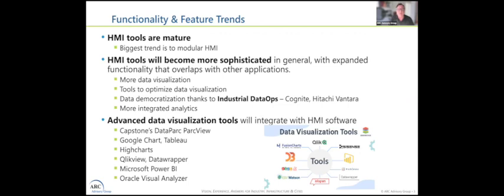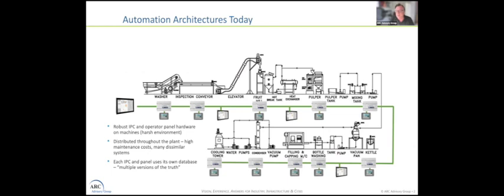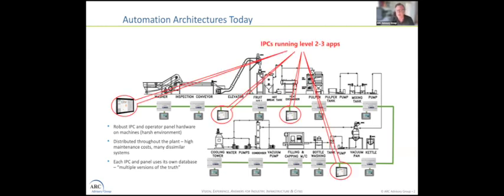HMI, when I refer to it, can be one of two things, really. If I just go back, it's those operator panels, which are a closed device that is configured externally and then connects usually directly to a PLC and is only associated with that PLC. And then there's the PCs that I mentioned that are on the line and can exchange data between PCs and between PLCs. An operator panel is a closed system with a configured visualization. An IPC is an open platform.